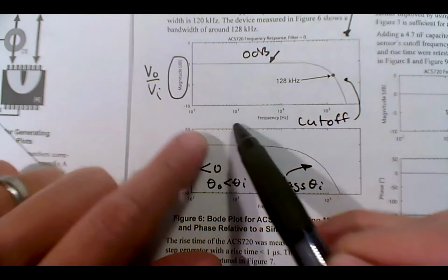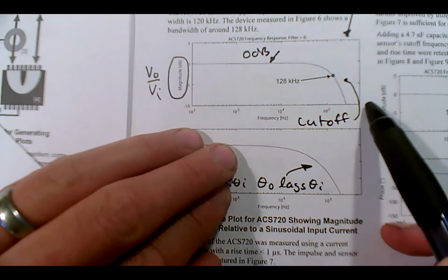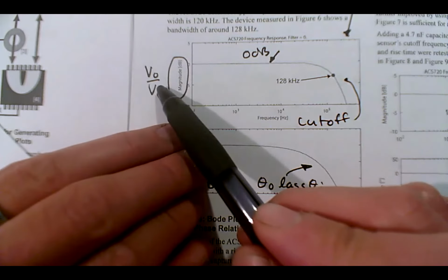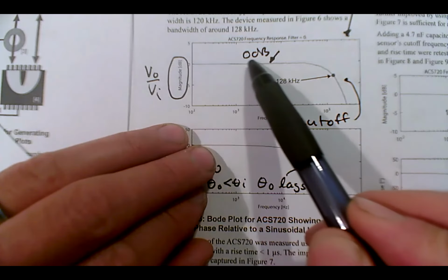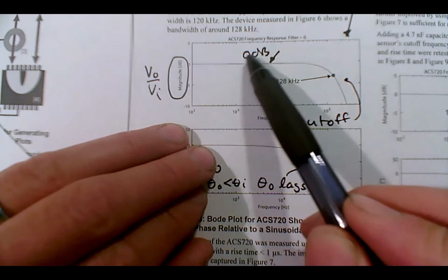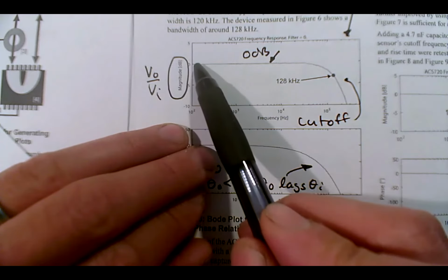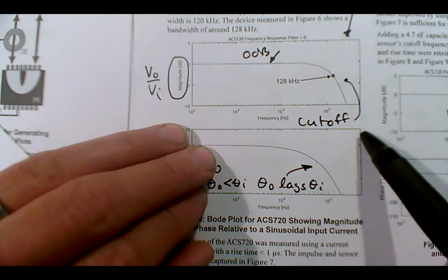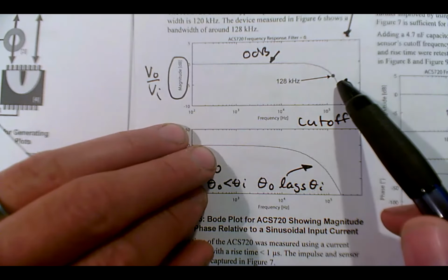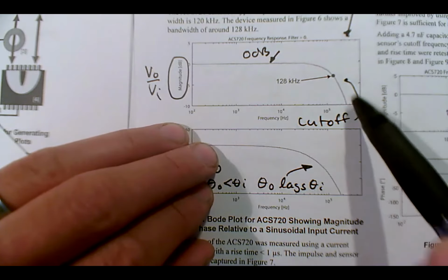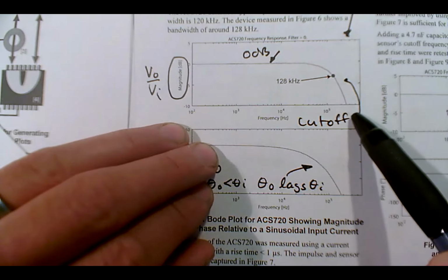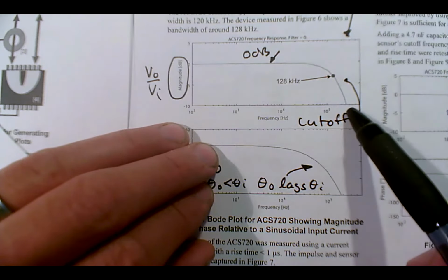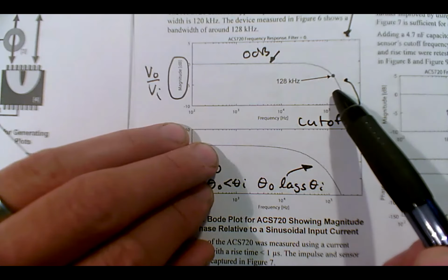So look at this, you have frequency in a logarithmic scale and you have the gain. This is defined as the output over the input, right? This is G. And look at this, you have 0 dB and you're like, 0 dB, why isn't that 1? We'll talk about that. This is like a gain of 1, and then you can see that it falls off. And you might wonder, well, wait, does that go off to negative infinity? On a dB scale, yes, it does. But we'll talk about that too, that this actually goes to 0 gain, right? But look, this is saying that the gain is falling off at high frequency. So this is a low pass filter, okay?